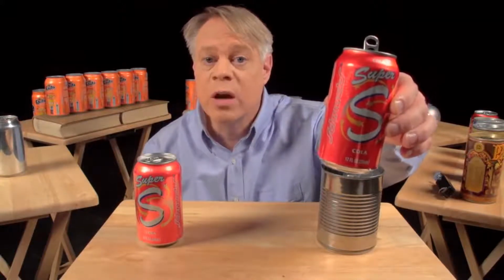So why is a beverage can pressurized? Because the internal pressure creates a strong can despite its thin walls. Squeeze a closed, pressurized can, it barely gives. Then, squeeze an empty can. It flexes easily. The can walls are thin, only 75 microns thick, and they're flimsy.